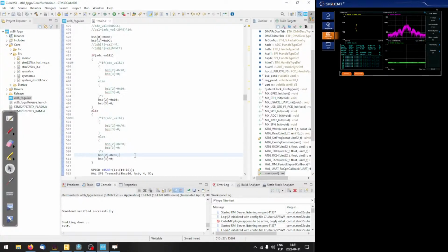So let's take a look at the spectrum again. We can see that there are two groups of points in the constellation. For BPSK, we actually expect the group of received symbols to be confined within the red circles that you see on the right-hand side of the screen. But if you look at the spectrum analyzer, in the upper left corner, there are two arcs that just switch sides from left to right.